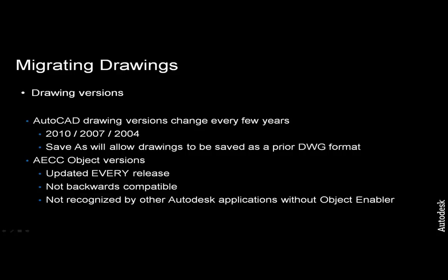Now let's discuss migrating drawings. It is important to understand the ramifications of migrating a drawing from one release to another. The first thing to understand is the AutoCAD drawing version that changes every few years. For instance, we are currently in a 2010 drawing file format. The previous drawing file format was 2007 and 2004.